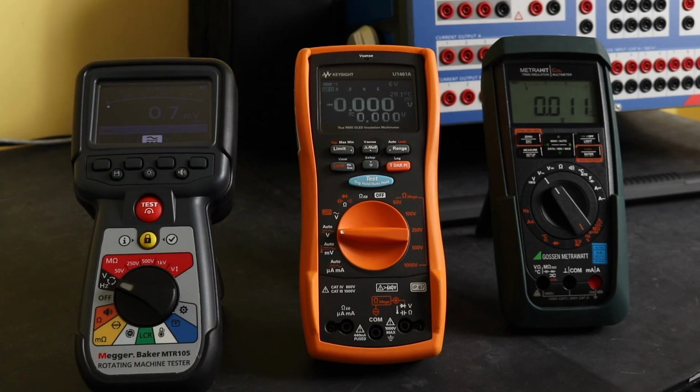Working on a motor, that should be fine, but if you take that Megger into distribution boards, perhaps need to be just that little bit more careful, whereas the other two would afford that slightly higher level of protection. For me, the accuracy and the resolution on the MTR105 is fine. If I'm measuring 415 volts, I don't care if it's 415.5 or 415.7, whatever it is, I'm not worried about that. Obviously some people may feel different, but for the kind of work that I do, I just don't need all the decimal points that the other two instruments offer, or I should say I very rarely need it, certainly when I'm not working on motors.